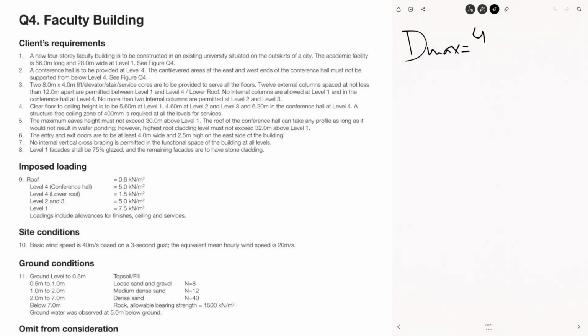So 4166 divided by 10 times the span, and I'll multiply by 2 because of the effective length, that is a cantilever, squared, divided by the E value of the steel, the elastic modulus, and that times the inertia that we just calculated, which is 3.85.